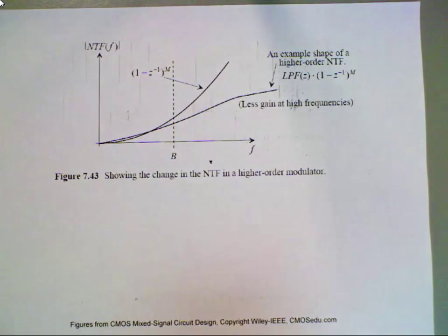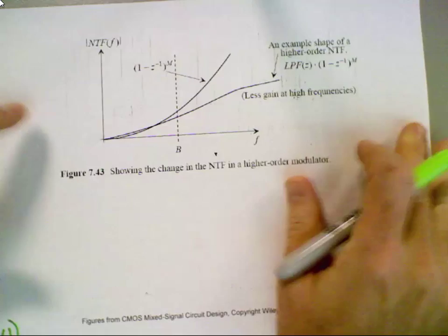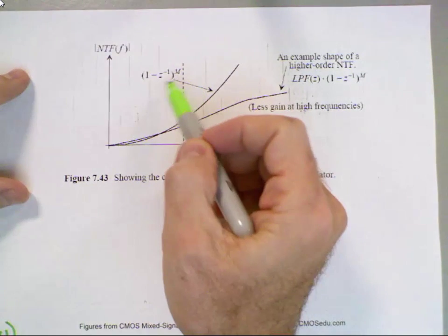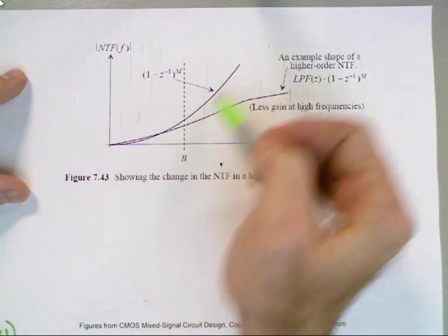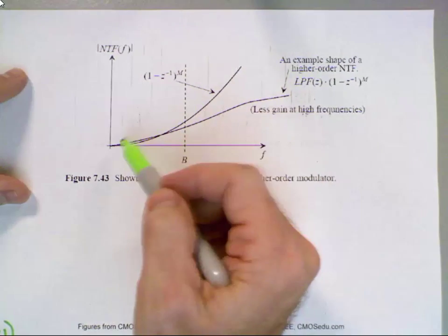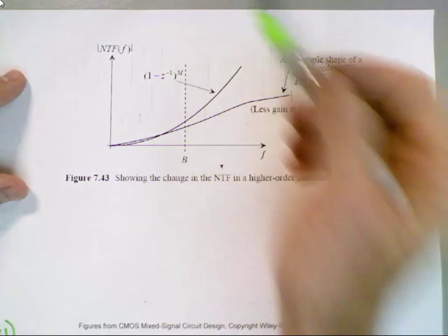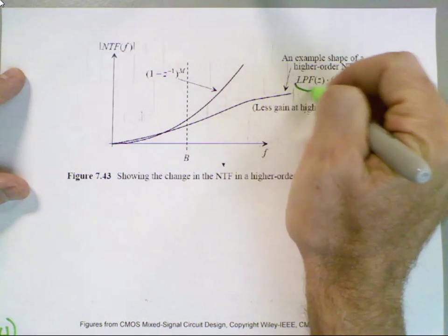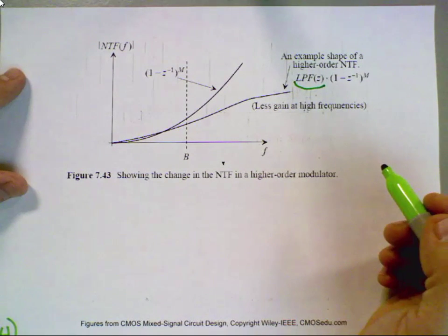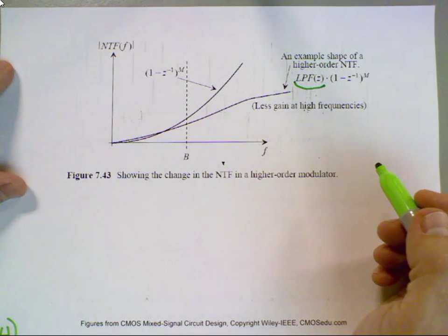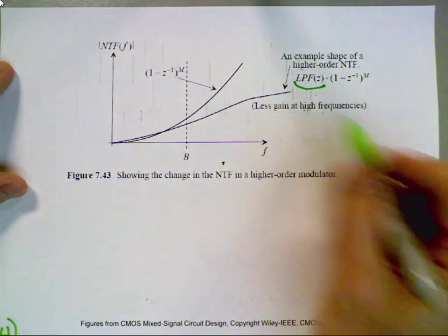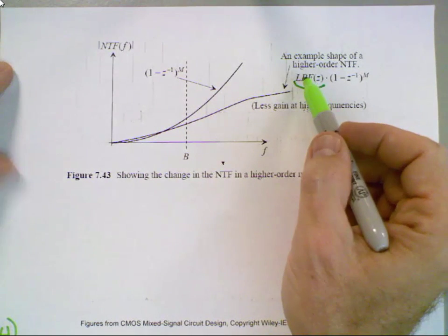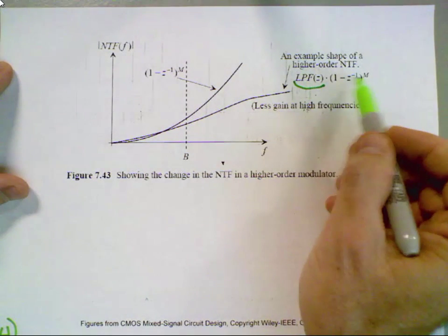Okay. The other thing is, if you look at the end result, here's what you get using M differentiators. You get this increasing and going up, and the bigger M is, the faster it goes up, as we discussed, right? Well, if you implement the feed forward with those coefficients, adding the B's in, then you can think of that as low-pass filtering the differentiation.